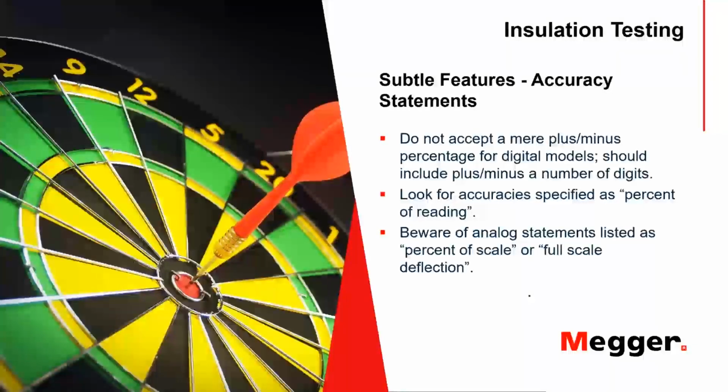And accuracy. Okay. Watch the accuracy statement of your equipment. This pertains more to the old analog units than it does now. But look, for instance, for percent of reading, not full scale. That's deceptive. You want the same accuracy at every reading, not just at the high end, because full scale accuracy on a logarithmic scale will change as it goes down the scale.